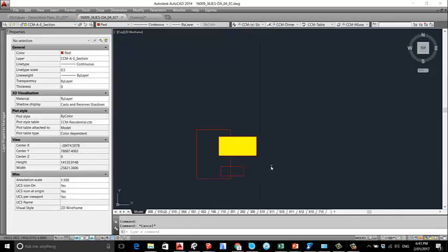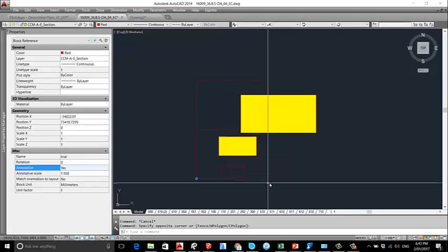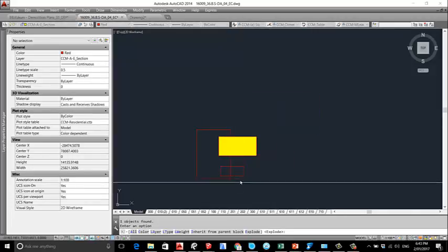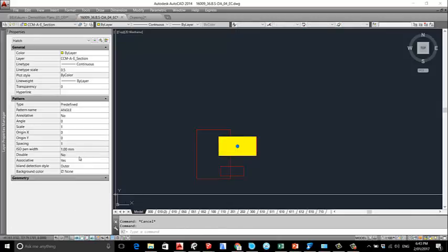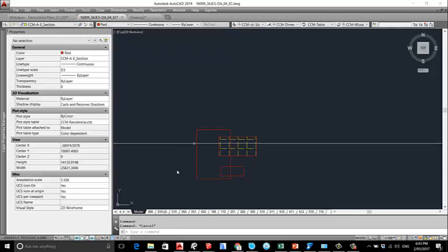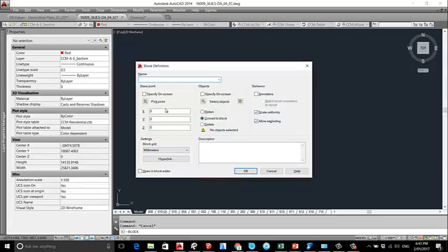Now we don't want this. So change this is impossible unless we explode the block and make it again the block. This scale is 1:100. It messed everything up. That's why all this thing of annotative scale has to be treated with care.